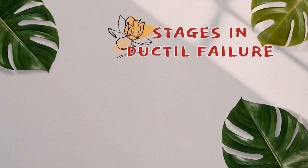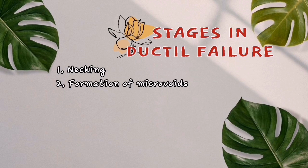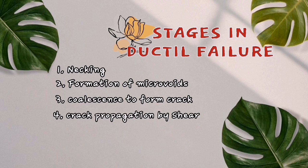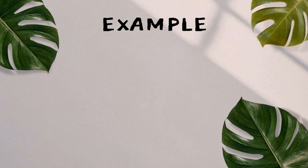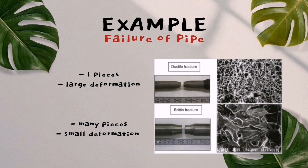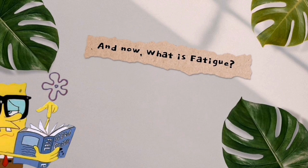The stages in ductile failure are necking, formation of microvoids, coalescence of microvoids to form a crack, crack propagation by shear deformation, and lastly, fracture. To make it clear, let's take a look at an example of failure of a pipe. In ductile failure, it breaks into one piece with large deformation. Meanwhile, in brittle failure, it breaks into many pieces and has small deformation.